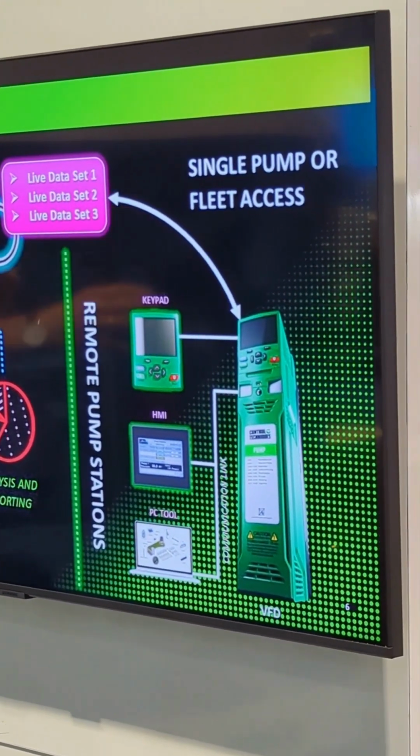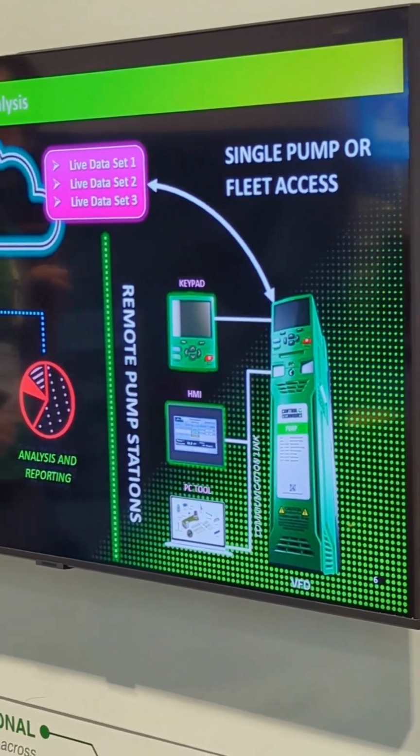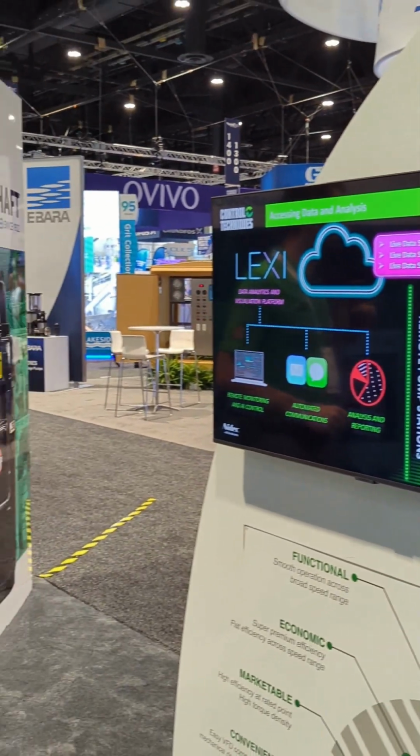So if something happens out of the system, you want to reset it automatically, you can do that through remote monitoring software. This also provides automated communications. Your pump goes down, it's getting dry, the drive is tripped, something happened with the motor. You get an email or a text automatically from this system in order to go out and remind you to reset it or to do it through your AI control.